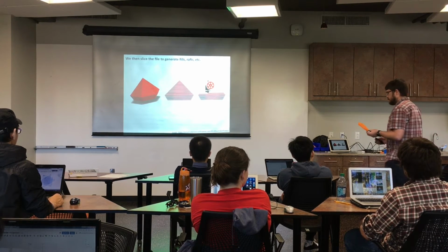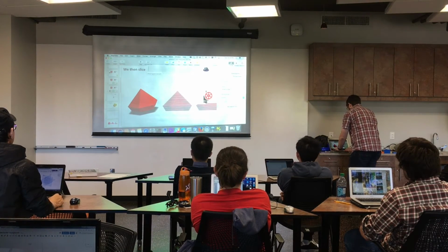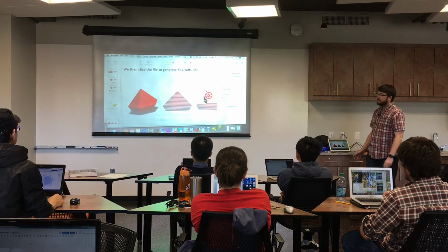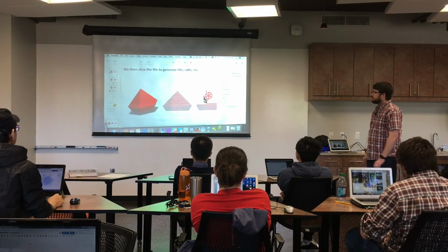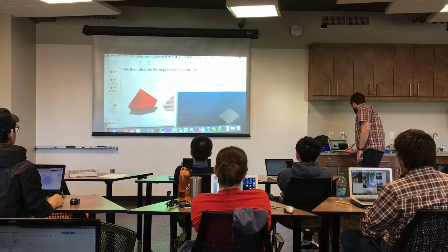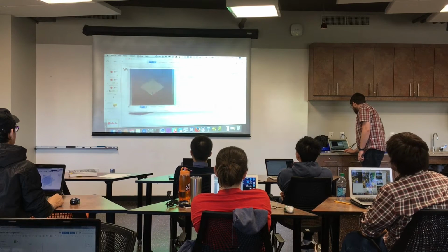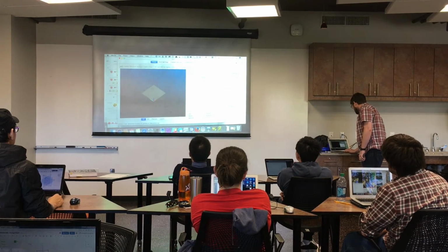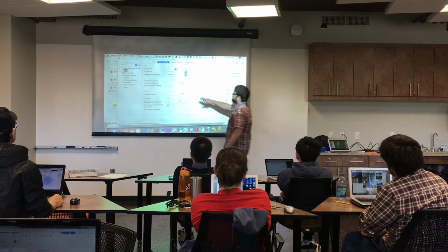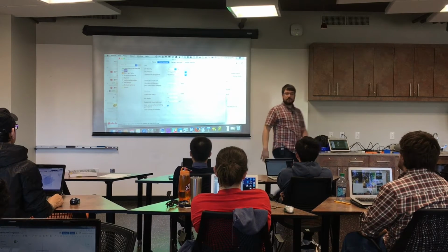Yeah. And there's lots and lots of things that you can change in there. I'll open up, this one is called Slicer. Different printer companies have different ones they recommend. Some of them even have their own. But in here, there's print settings, so I can change the percentage of infill, the pattern, how many, after so many layers do I want it to do a solid fill.